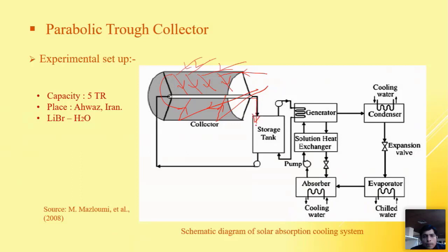the storage tank. This heats inside the generator, okay, and makes the system work properly without any use of, say, an auxiliary heater and all, and then it goes again to the pump. Then here also we may have a pump. So pumping may be required in all the processes because we need to move a liquid. Without gravity use, it is not very efficient, because thermosiphoning will not be very efficient here if we are not using a pump.